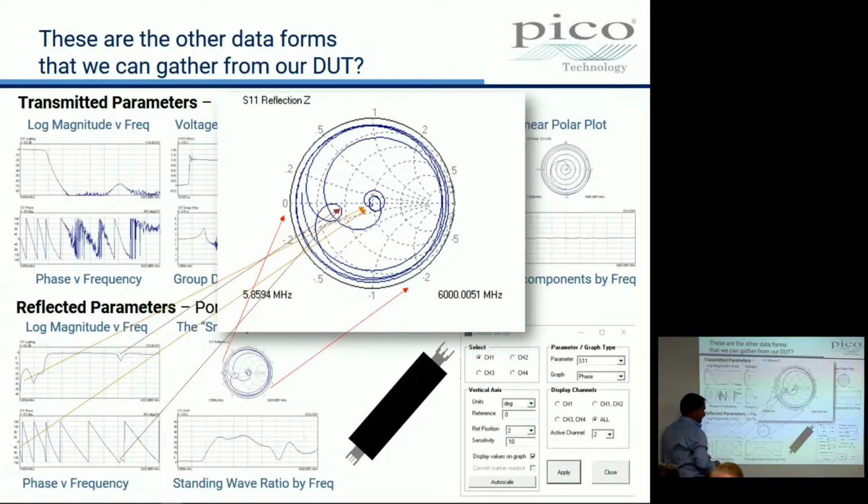And you might remember we talked about standing wave ratio earlier. That's the standing wave ratio. So what that's telling us is, in this dot, it's telling us Vmax over Vmin. It's pretty small, i.e. the Vmax over Vmin is 1.5 to 1.